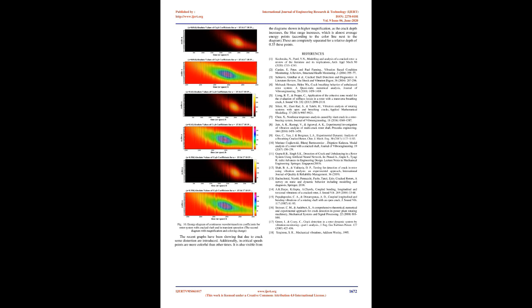In the case of displaying the Fourier transform with vertical axis on a logarithmic scale, there is some difference in amplitude at the beginning of the period. In magnified graphs, some small peaks are visible. Moreover, these low-amplitude peaks correspond to the cracked shaft's period of rotation. As the depth of the crack increases, these peaks can be more apparent, due to a growth in their amplitudes.